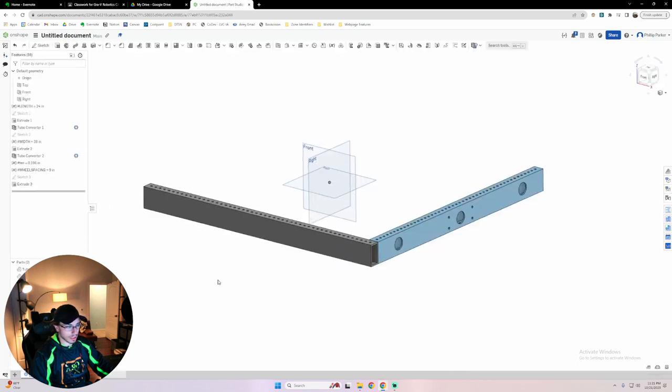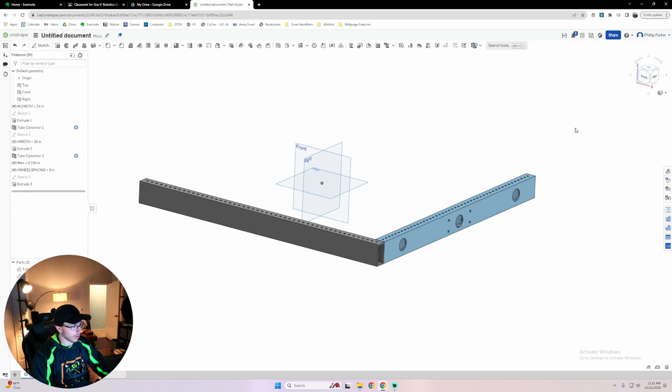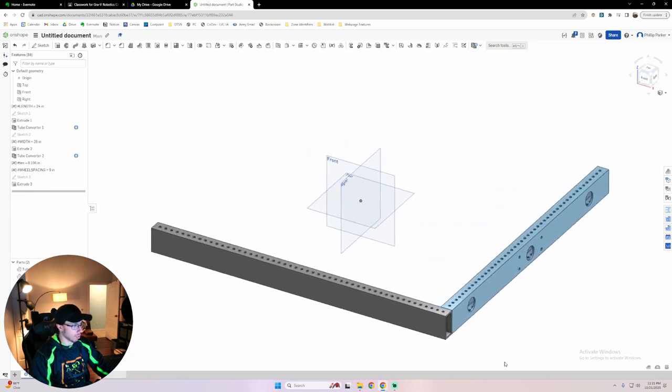Now, one of the things that we didn't do before that can be particularly helpful when you go from one assembly to many assemblies is creating a reference cube, so that all of your constraints can be done off of reference cubes. You can mate the reference cubes together.